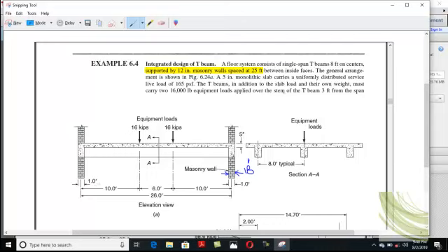Suppose this is 12 inches, therefore 12 inches equals 1 foot. And the 25 feet is the clear span inside. The clear spacing is basically 25 feet, and the center to center spacing is 26, because 0.5 is from this side and 0.5 from that side. Clear?